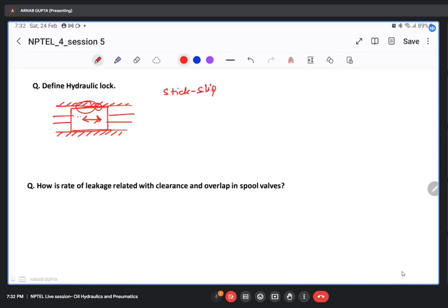It is sticking again, that contact. Suppose you look at the micro level. These are the two mating surfaces. As it is translating over this surface, at these pointed tips, the Hertzian contact pressure is very high. So they tend to get welded at these particular points due to the Hertzian pressure, and as a result, they stick with each other.